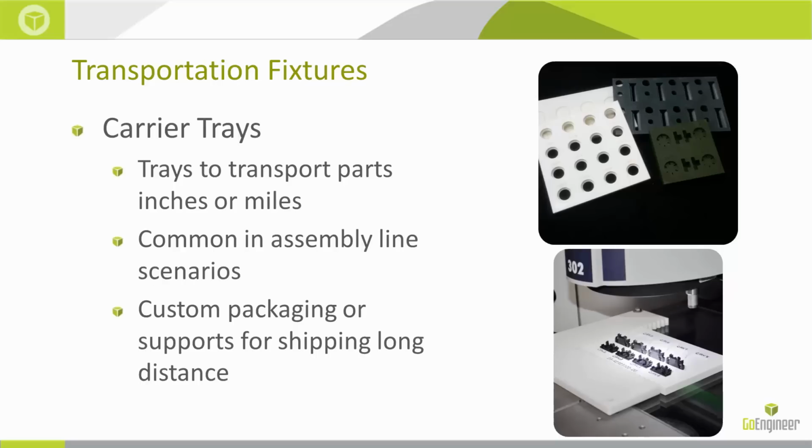But almost always what we did, especially for the more complex shape parts, is we created trays. Something that could be very easily stacked, and the parts when they're on the tray would be nice and organized and nothing would get mixed up, and it would allow the workers to sort them and whatnot. Those trays were kind of tricky to design because we were always trying to design them in ways that were easy for the machine shop to cut, because we didn't want full 3-axis, 5-axis surfacing on these trays.